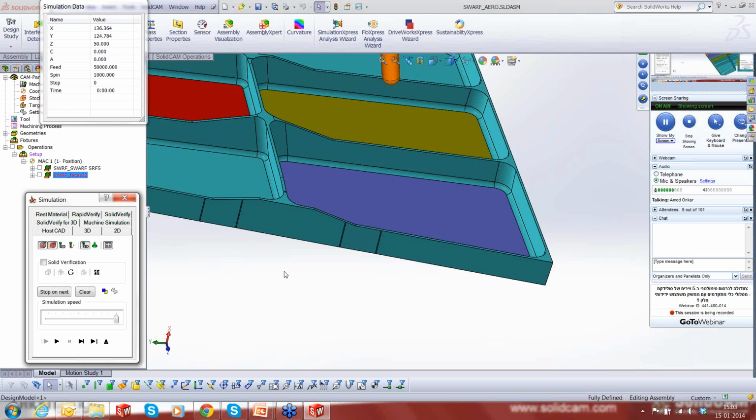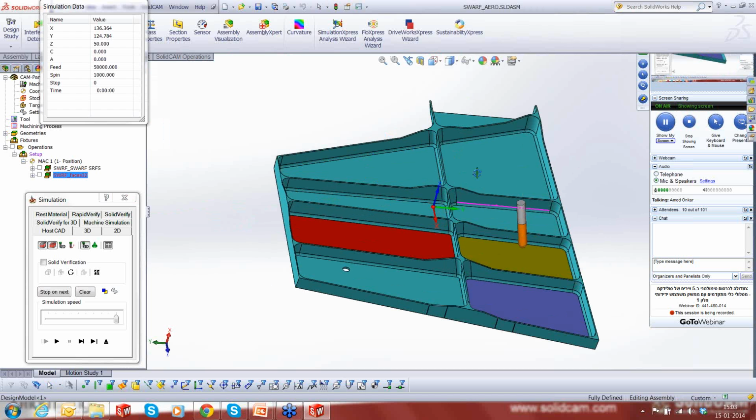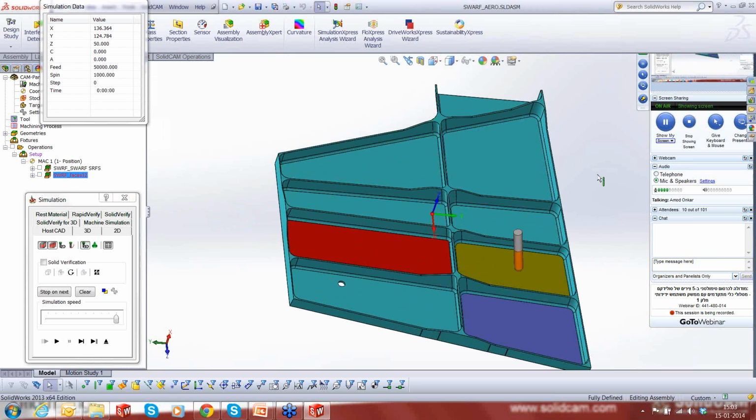Where all can you use it? Well, application-wise, the first application that I can think of is machining of such frame parts, where generally people would machine this using 3-axis. They'll go with multiple depths of cut, whereas with 5-axis you could just go single cut, eliminating all those multiple cuts and save a whole lot of time.